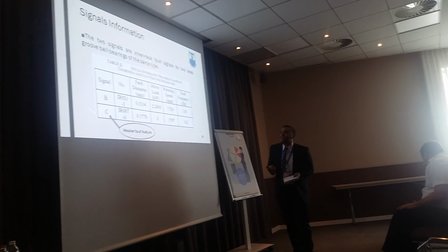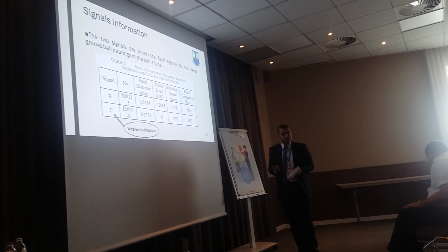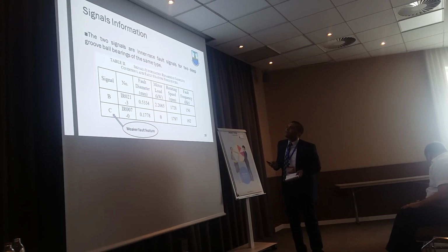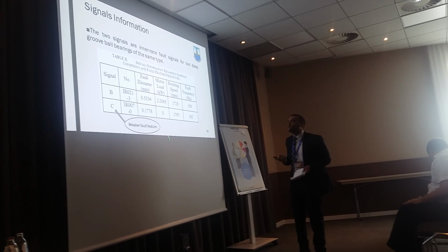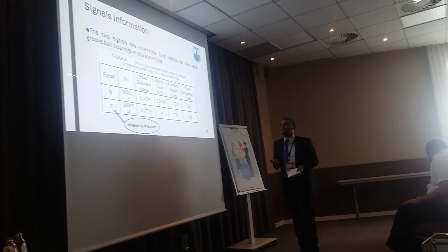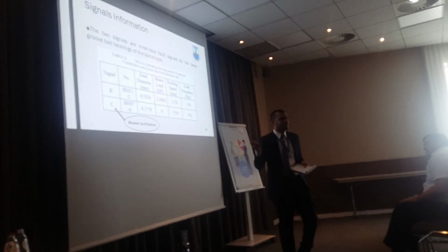Whereas signal C has a zero motor load. The motor load is very low, zero. And the fault size is smaller, which will result in a weak fault feature in the signal. That means that the diagnosis of signal C will be harder than signal B.